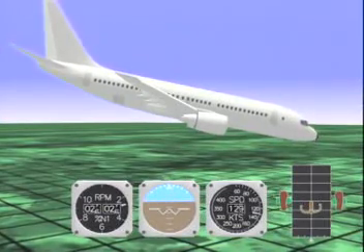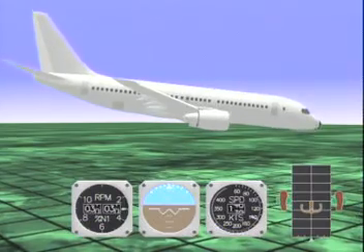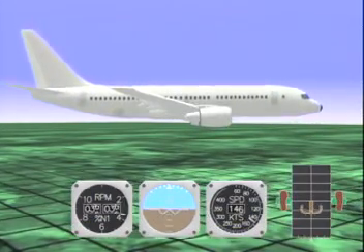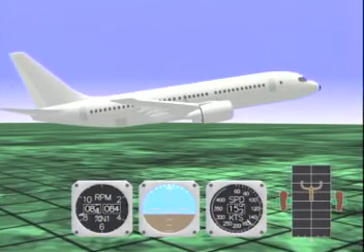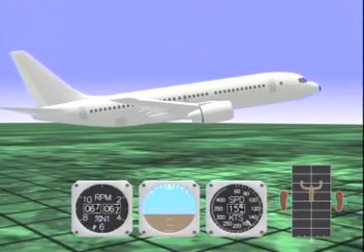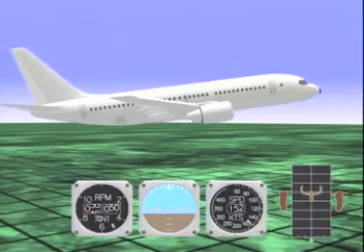Once recovered from the stall, apply thrust. The nose must be returned to the desired pitch, avoiding a secondary stall, as indicated by stall warning or buffet. Respect the airplane limitations of G-forces and airspeed.